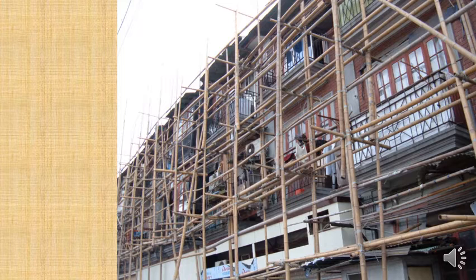useful is for scaffolding. Now, I think here in Kurdistan, for the most part, people are using aluminium scaffolding these days, but in many parts of Asia where bamboo is quite regular, quite available, they will do scaffolding out of bamboo. It's very stiff. It's got very little elasticity. It won't bend and twist in the wind, and the tensile strength is such that actually people can walk across it, and so it's very good flexural loading.